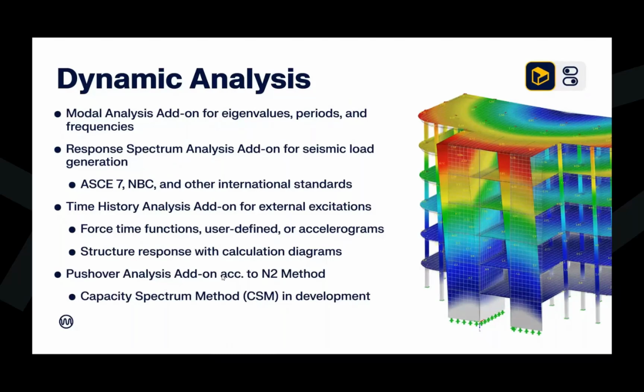So if we are interested in carrying out a seismic load generation, we would want to utilize the response spectrum analysis add-on. So within this add-on for seismic loads, we do have the codes implemented here, the ASCE 7, the NBC standard. And with the response spectrum analysis, this is applicable to any structure type. And that's why we've taken this approach with the response spectrum.